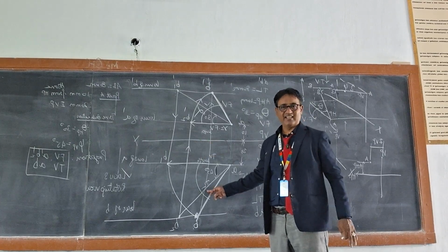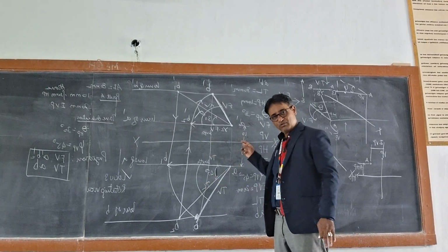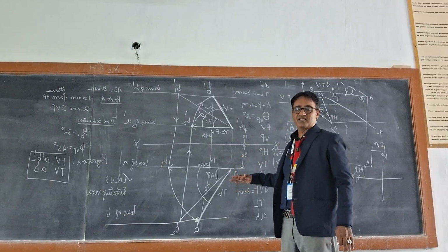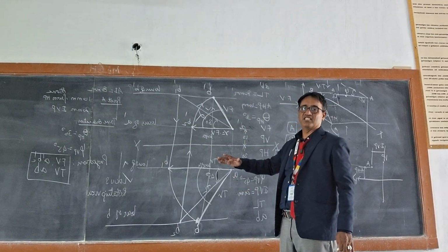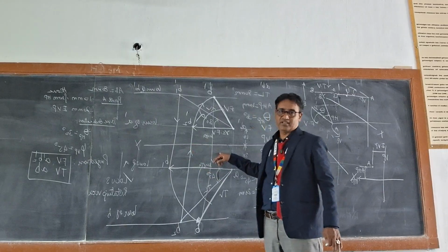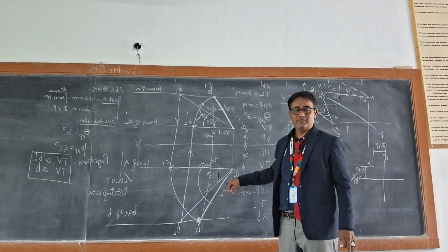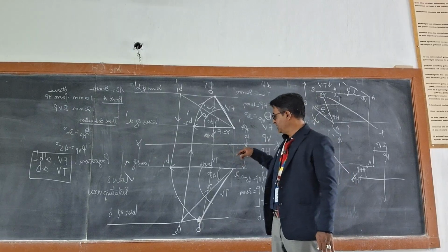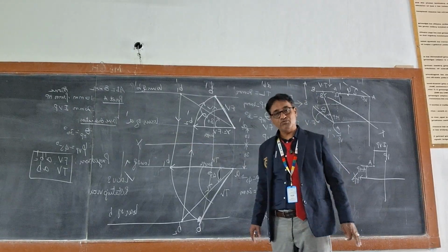When I am saying angle, it is with respect to xy, but since the points are displaced at some distance from HP and VP, you are drawing this locus which is parallel to xy. So when I say angle, directly or indirectly it is referencing the reference line xy.